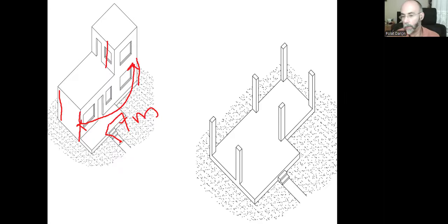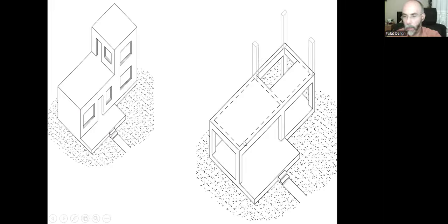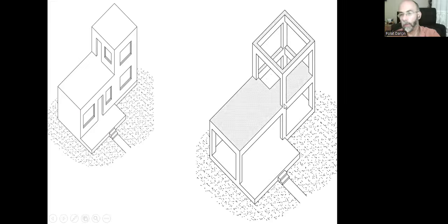And if the gap is more than 7 meters, then it needs columns, obviously, here, like that. These columns will go upstairs as well. That's what we do. We connect them with beams and we go upstairs. We place the floor slab here and do one more floor like that. That's what we prefer in normal conditions.